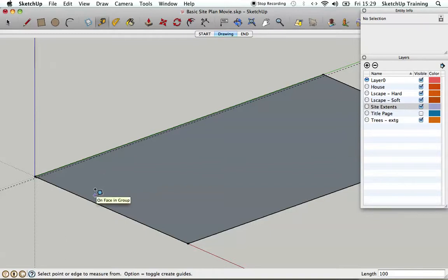So I can do that again now for the offset of the house from the bottom of the extent. This time we want a metre, so I've selected my ruler tool, I'm dragging it out anywhere, I'm going to release it, now I'm going to type in 1000 and it will go back to 1000 millimetres off this bottom edge, so from there to there is a metre.